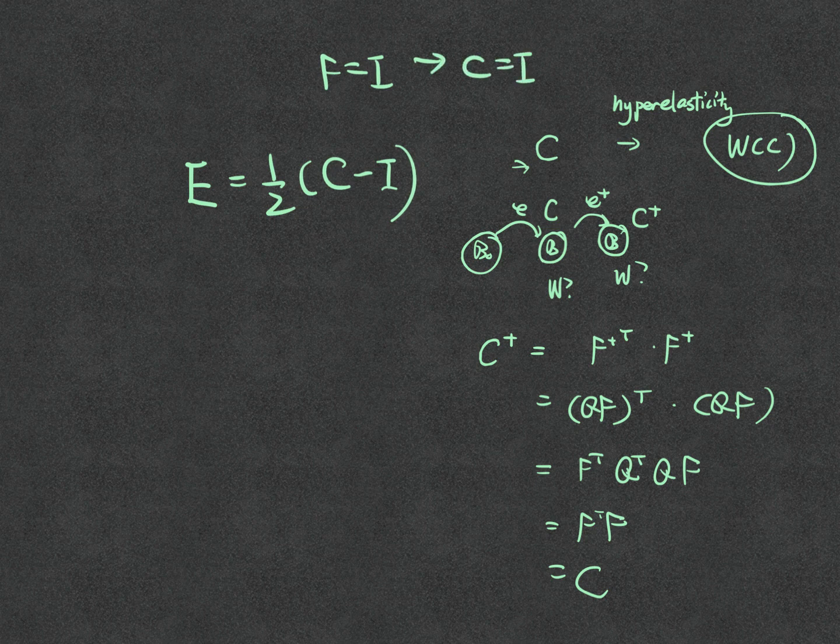But this is not always convenient, because if I write the functions, then I would have to take the identity matrix as the input and then output no energy. Then I don't have the homogeneity that makes the model writing easier. So sometimes for convenience, we use E to write a constitutive model, not for any specific reason, just to renormalize it, in my opinion.